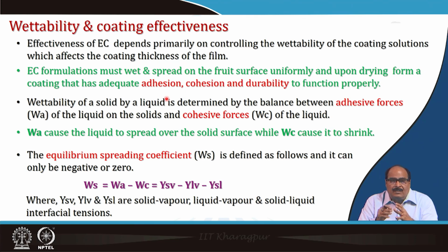Wettability of a solid by a liquid is determined by the balance between adhesive forces, that is WA, of the liquid on the solid, and cohesive forces, WC, of the liquid. WA causes the liquid to spread over the solid surface, while the cohesive forces WC cause the liquid to shrink.